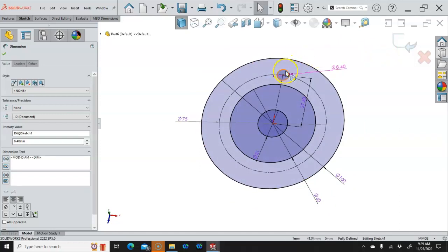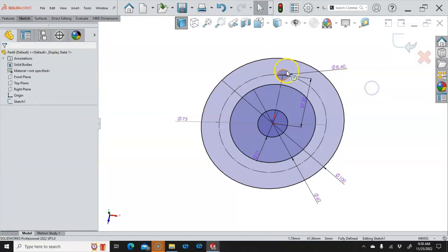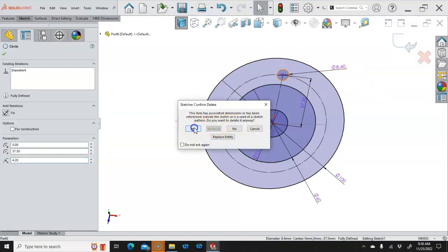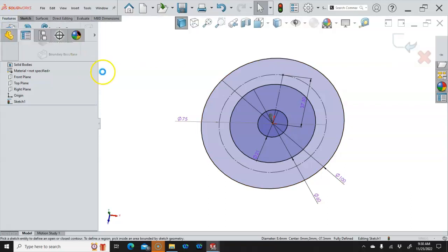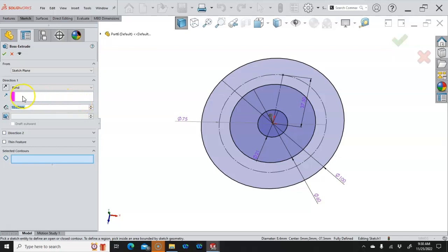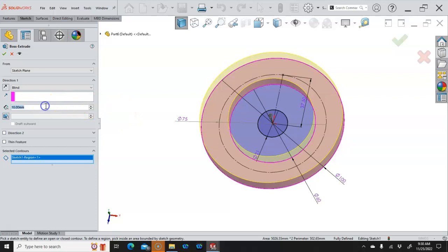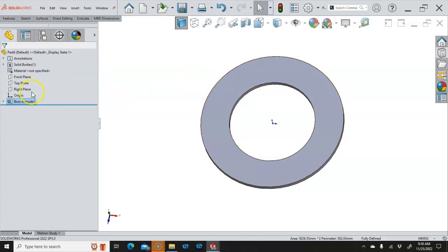And if I go that route, then I can't do the feature pattern. So maybe I would have to do the circular pattern to include that. So let's just go ahead and I'll delete that back out, and we'll extrude this up to 3 millimeters. All right, so it's going to contour and region. We need to select inside the area that we want and accept. Hides the sketch automatically, so we're going to show.